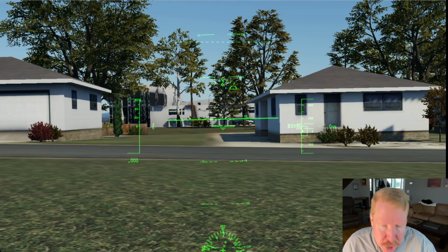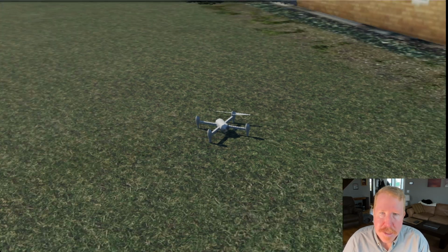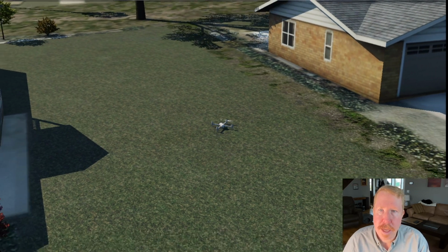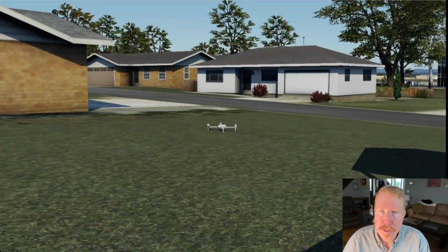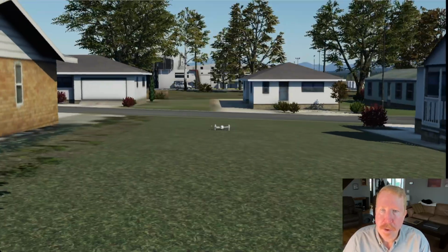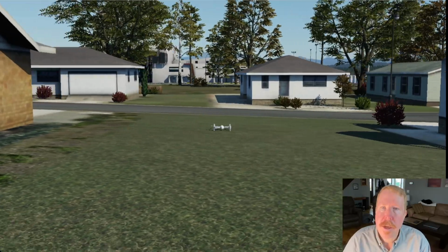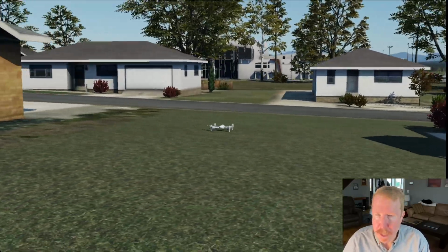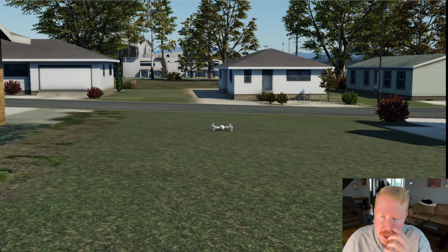What I'm going to recommend is Shift 2. This is what you see when you really operate a drone. Shift 2, and then I'm going to hit the less than sign on the keyboard. That's going to back me away from the drone, or the greater than sign to move in. So I'm hitting the less than sign to move away, and I can do the arrows to move up and down and left and right. So I'm sitting here hitting the less than sign and greater than sign and the arrows to move my view around. Okay, I think that's the view that I want.